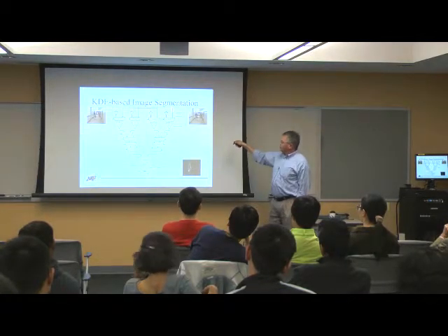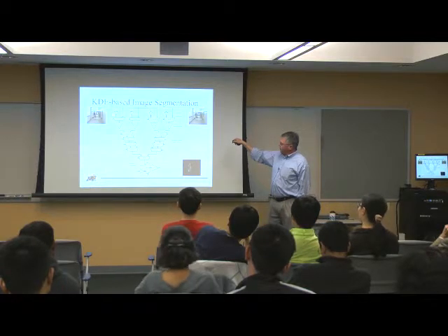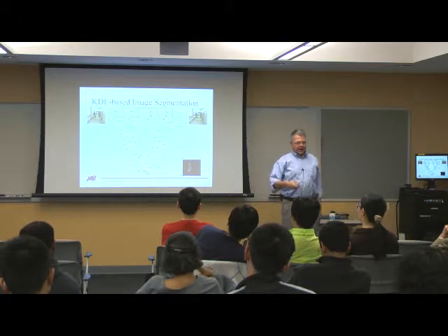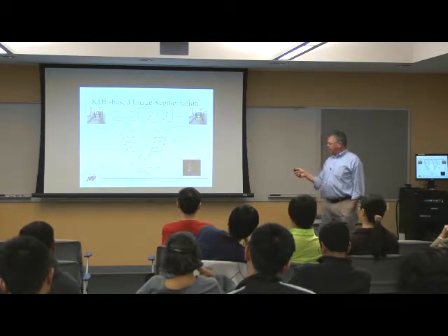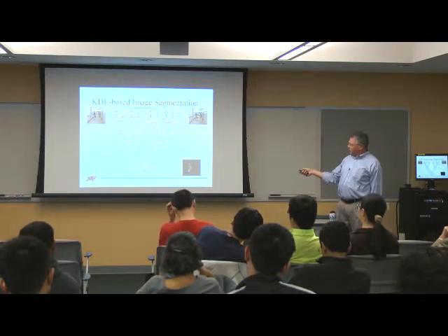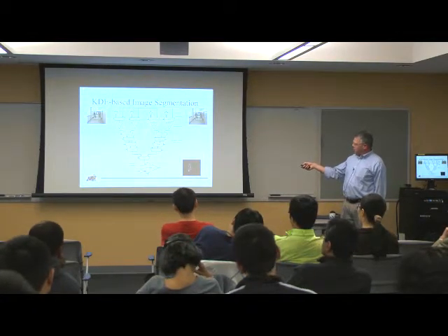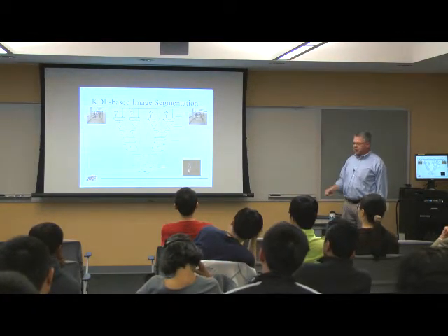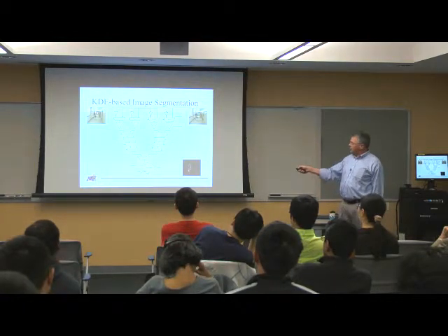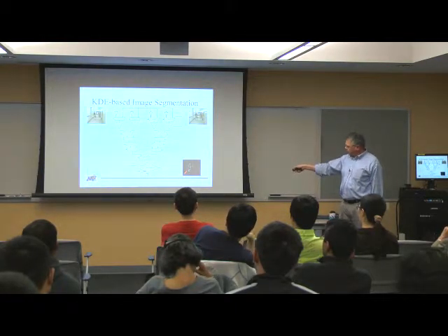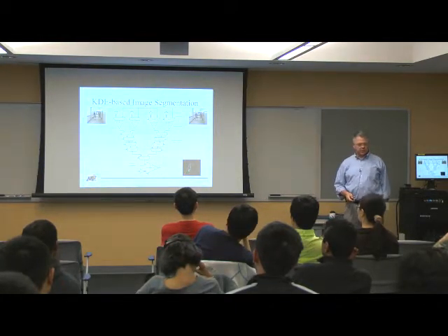Here's the current image, xt. Here's all the other images back. In this case, I go 32 images back, 32 frames back in the sequence. And then I do this exponentiation operation through here, and I do some summing, and then coming out here is that thresholded value. So for each pixel of these 32 images, the sequence of 32 images, I run it through the circuit, and then I get this result coming out here.